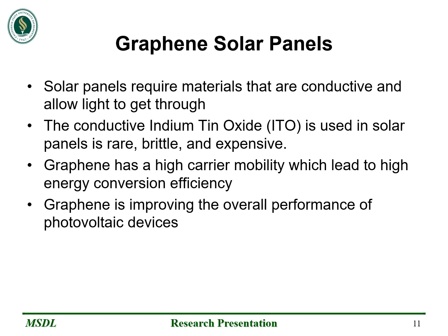In a traditional photovoltaic cell, light is absorbed by a semiconductor material, creating an electron-hole pair that is separated by a p-n junction. The separated charges then flow through the cell as an electric current, generating power. However, during the separation process, a significant amount of energy is lost as heat, which reduces the overall efficiency of the cell. However, by using graphene to create a hot carrier cell, it will capture the excess energy of the excited charge carriers before they thermalize and release their energy as heat.